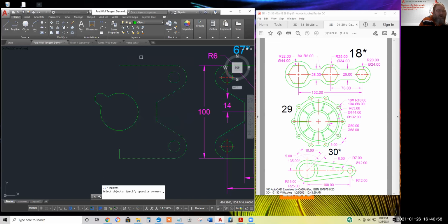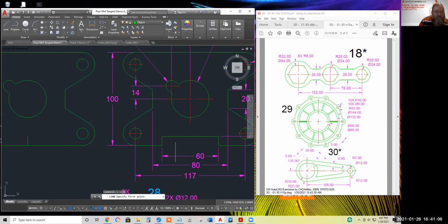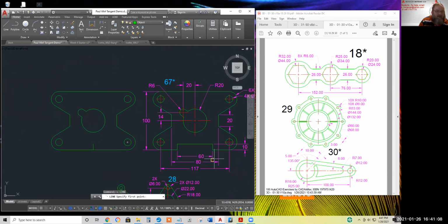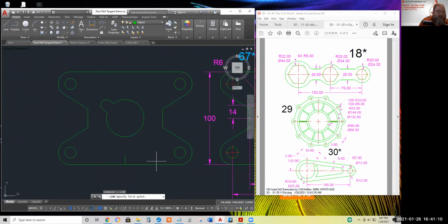Great big crossing window, enter. 2 quadrants right there. And let's see, I think this is 60 across. I don't have to do the arithmetic, you know, divide by 2 to calculate that as 30. I can just make the line 60, enter, and move it from its midpoint to the end point.